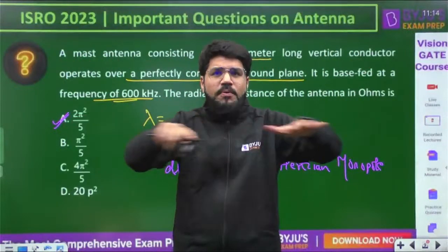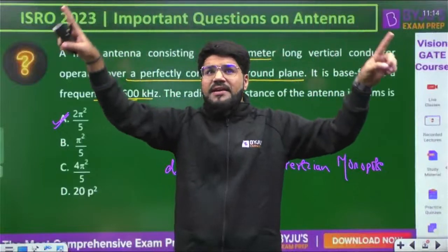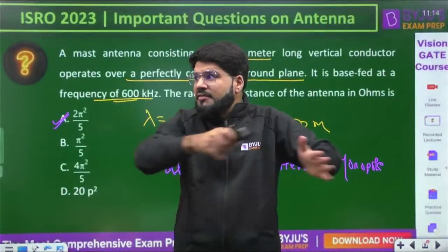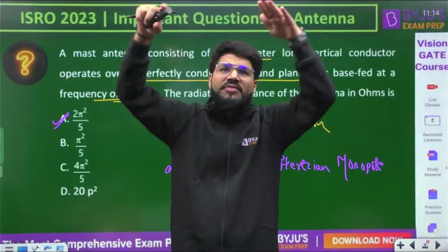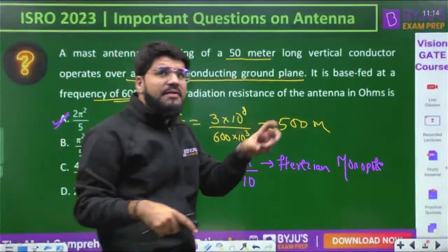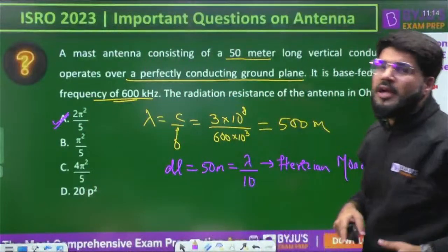Okay, if there was no grounded plane, the radiation of the antenna is usually in all directions, spherical direction. But when the source is placed above an infinite grounded plane, it can only radiate above that ground in the hemispherical portion. And that is why the radiated power is 50% of what a dipole can produce.